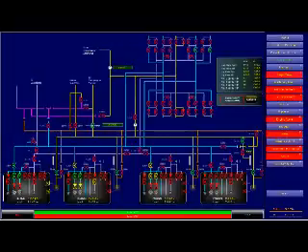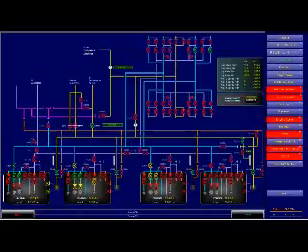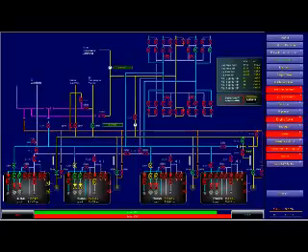Are you set up with the line? No, the tank. Think about it. You will have to take the vapor from the shore. So, initially, don't open the discharge line. You will recirculate within the tank. Okay? The rest of the lineup, you set discharge here. It is already, vapor is going out.